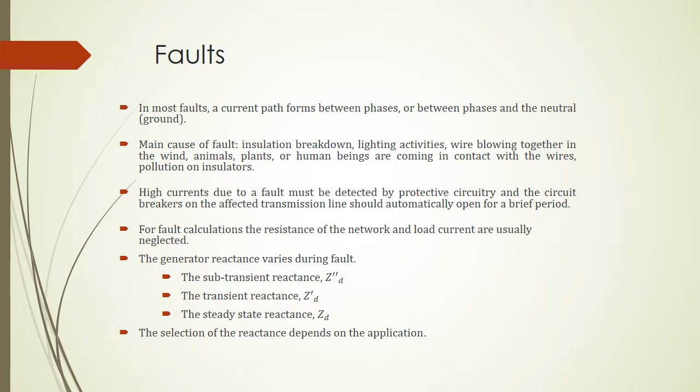our devices. When we do the fault calculations, usually we neglect the resistance of the network and the load current because the fault happens very quickly, and therefore reactance has a much bigger impedance here.